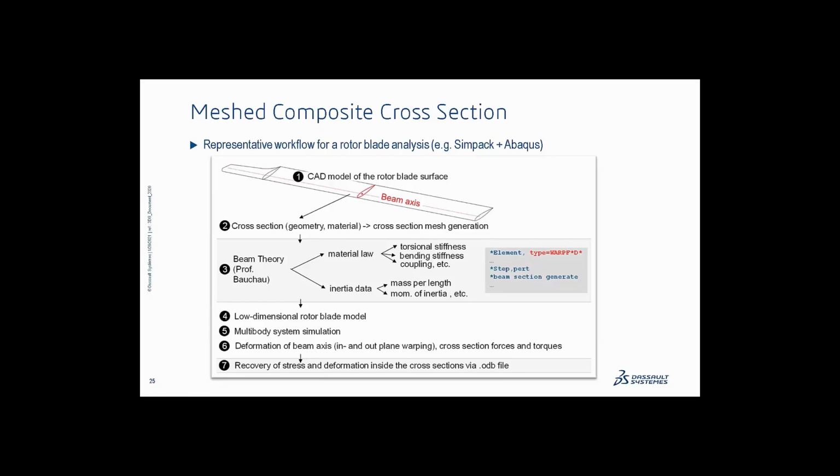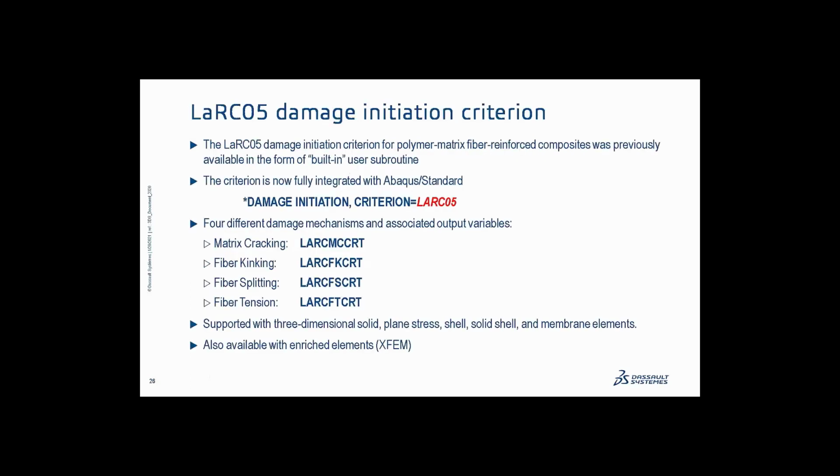And obviously the outside of this can be driven by an optimization typically. Today, these matrices that are generated as a result of the warping are dense, so unfortunately at the moment we can't run them with the Abaqus beam general section. But that's an enhancement that's currently in progress: enhancing the beam general section so that we can use these dense matrices from the meshed composite sections directly in Abaqus as well.